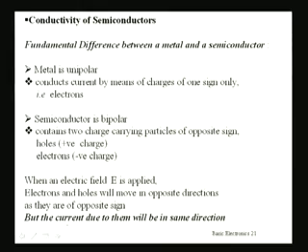So we have got this fundamental difference between a metal and a semiconductor in the way that metal is unipolar, since current conduction is taking place only by electrons, which is having only one sign, that is negative sign. But in semiconductor there are two charge carriers having negative as well as positive charges, which are known as electrons and holes. So semiconductor is a bipolar material.